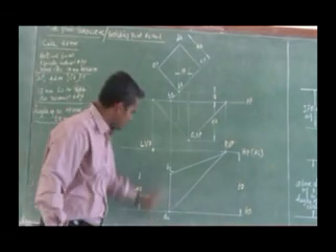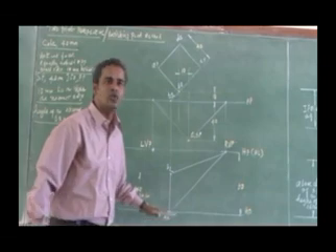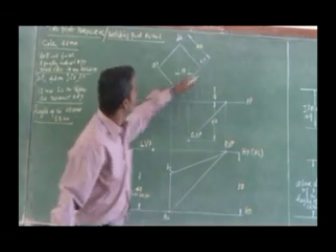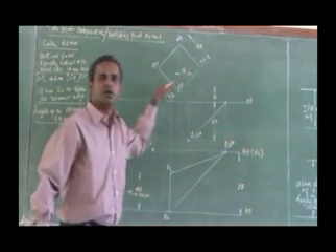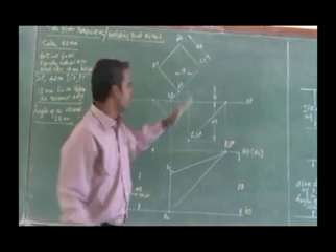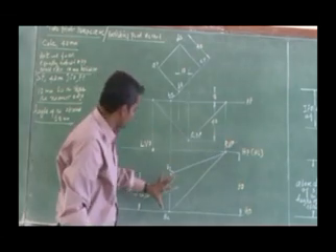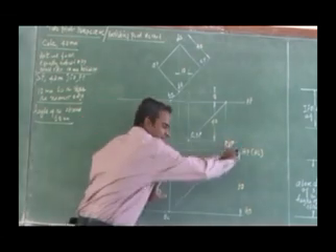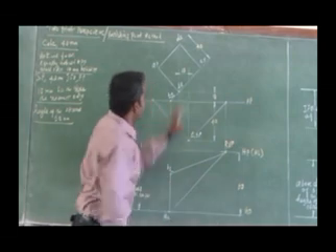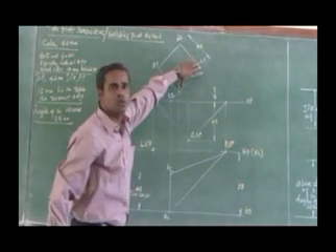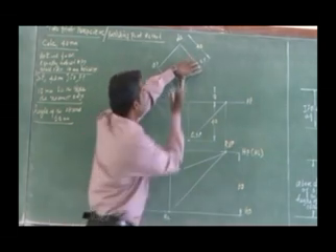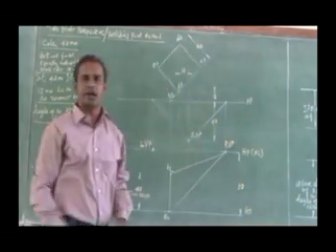Are you clear with this? I have drawn B2 Q2 and am drawing two vanishing lines for this face to get its perspective, because this face is going to vanish in the right vanishing point. So B2 Q2 is marked down. Within this vanishing line, I have to get the perspective view of this face BQCR.